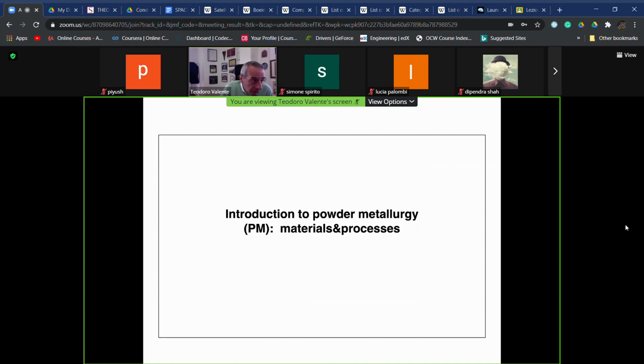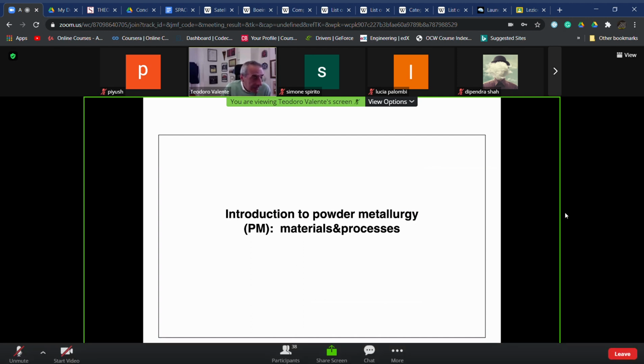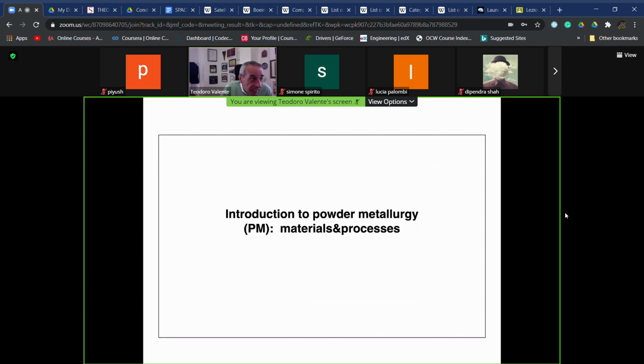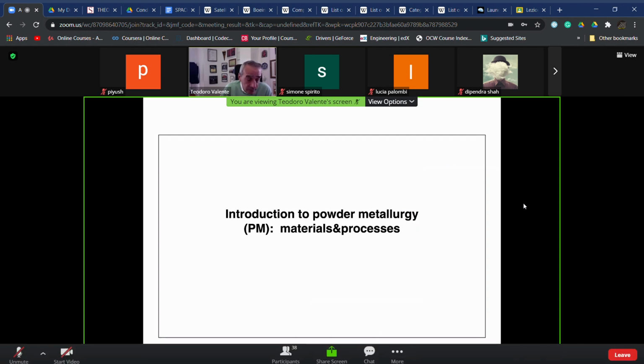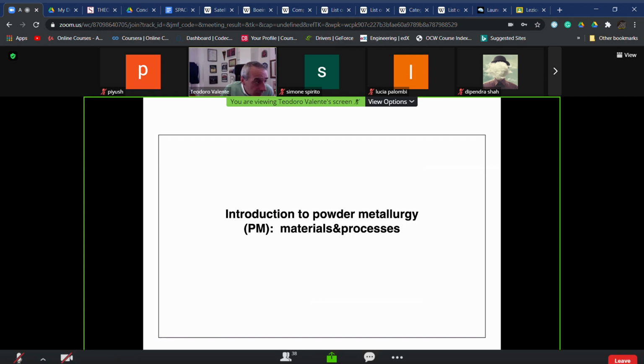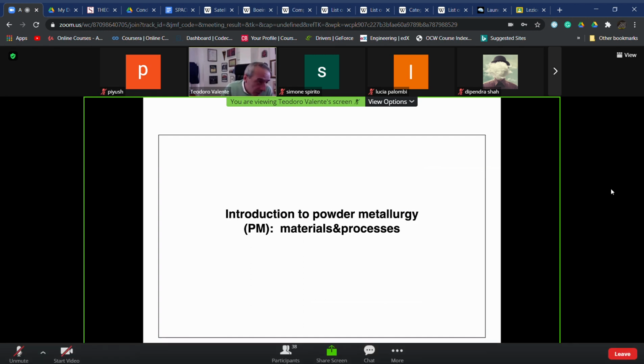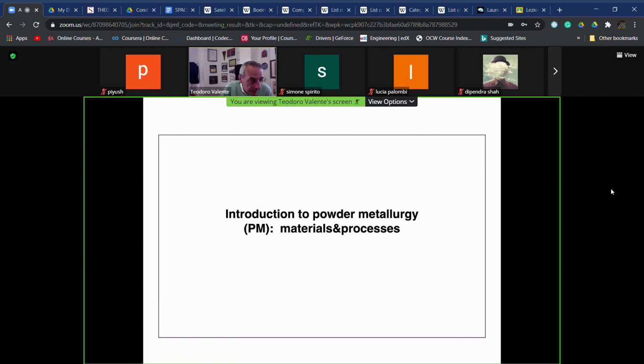Because the ceramic phase, which is lighter than the metallic phase, the metallic base alloys, will no longer retain its homogeneous distribution if put in a liquid phase. Then it can also experience grain growth, which depends on the starting powder, but that's another matter.